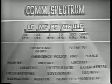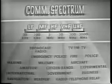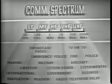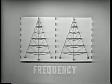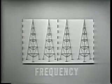And you can see what's happening. The frequency spectrum is already too crowded, and getting more so every day. Now, this is a serious problem. So electronic engineers turned their attention to solving it. There were two possible solutions. One, to increase the efficient use of transmitter power so that more distance could be obtained, which would enable fewer transmitters to cover more of a given area. Or two, to narrow the frequency bandwidth required for each radio signal so that more frequency space would be available for additional stations.